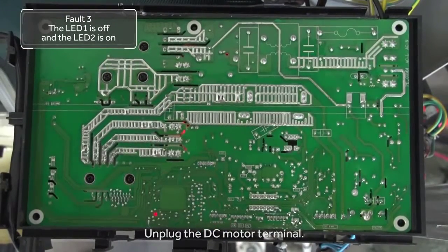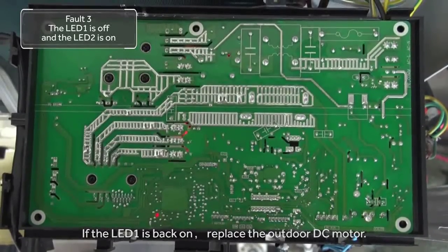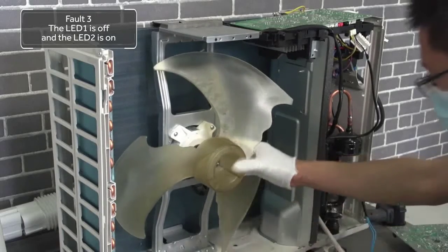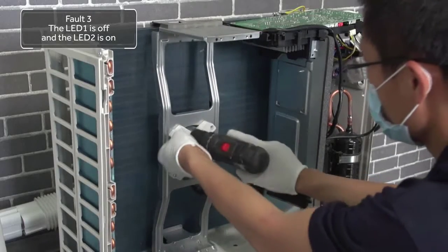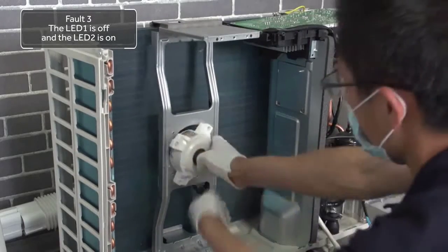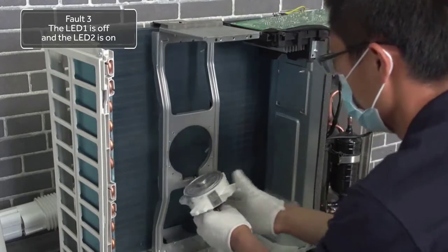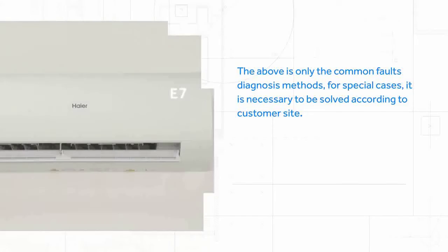Unplug the DC motor terminal. If the LED 1 is back on, replace the outdoor DC motor. The above are only the common fault diagnosis methods. For special cases, it is necessary to solve them according to the customer site.